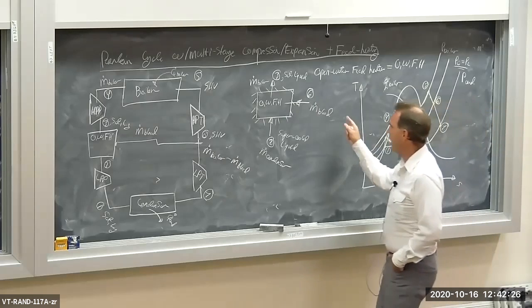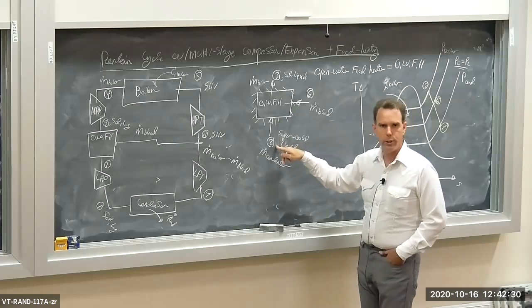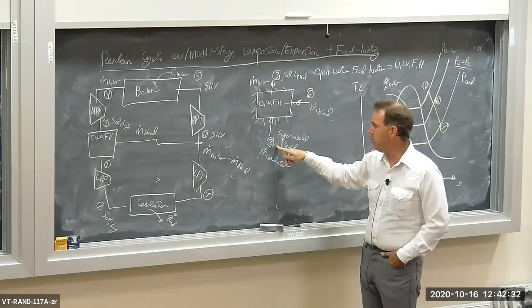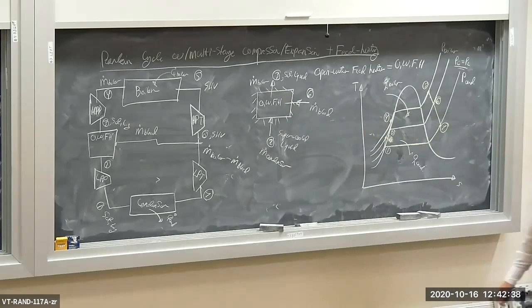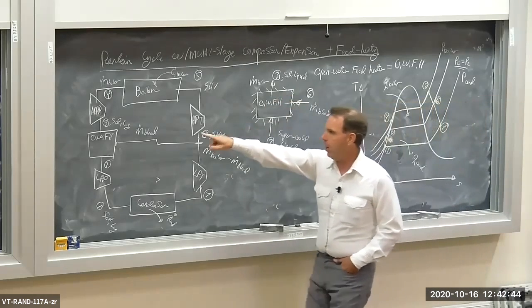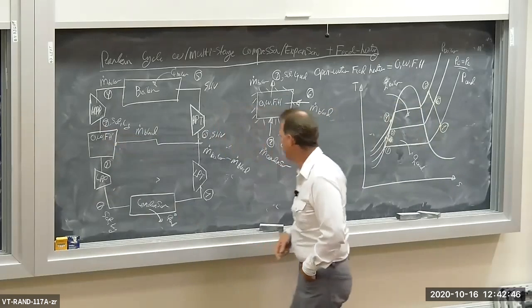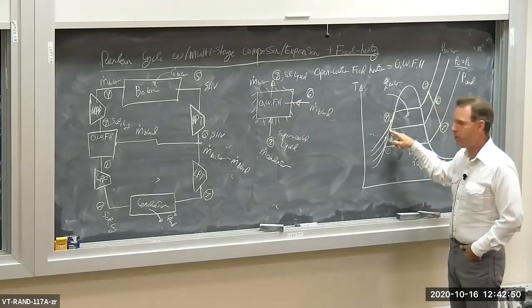So we're going to take high energy steam and low enthalpy supercooled liquid, and heat it up to a saturated liquid. So we're going to increase the enthalpy of the flow going into our high pressure pump. We end up with a saturated liquid at state 3 going into the high pressure pump.